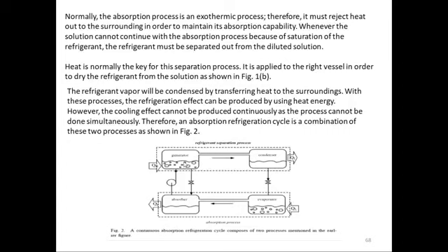and the refrigerant will come out of it and go into the condenser, and the high concentration solution will come out here, back into the absorber. Because some of the water is already gone, the solution has a higher concentration here, and that will come back here. And this is the valve which will keep the pressure difference between the two. This is the pump which is creating the pressure difference between the absorber and the generator.